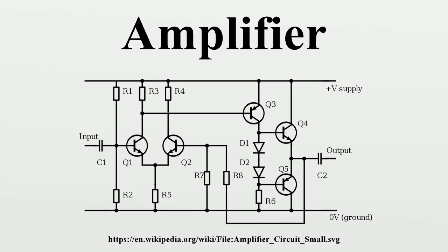The types of amplifiers can be categorized in different ways. One is by the frequency of the electronic signal being amplified. Audio amplifiers amplify signals in the audio range of less than 20 kHz. RF amplifiers amplify frequencies in the radio frequency range between 20 kHz and 300 GHz.